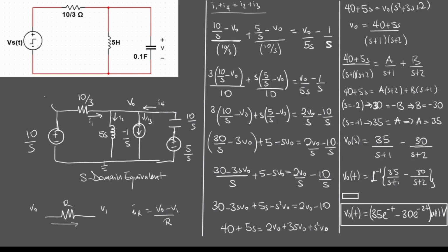First of all, do you understand how I'm choosing to solve this? The question told us to model inductors as a current source and capacitors as a voltage source. But if we wanted to do it our own way, since we have these guys in parallel already, we could model this as a current source and also model this as a current source, if we wanted to solve things as straightforwardly as possible. And if we wanted to go a bit extra, we could even source transform this to something this way, and this will now become a current source.